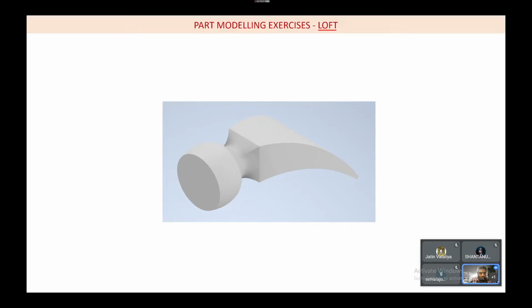I select this point, again 25 mm, the same direction. So now I'm going to draw a bigger circle. I hope you guys are also able to follow. If you also have Inventor opened on your computer, you can also parallelly try this solid with me.